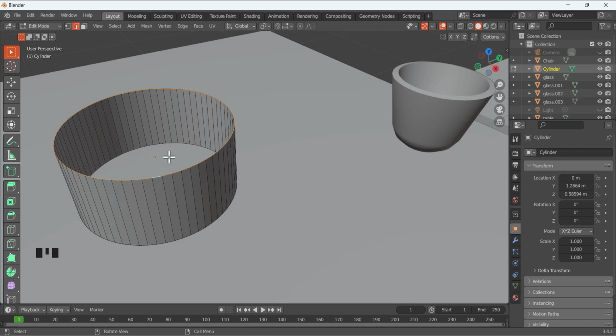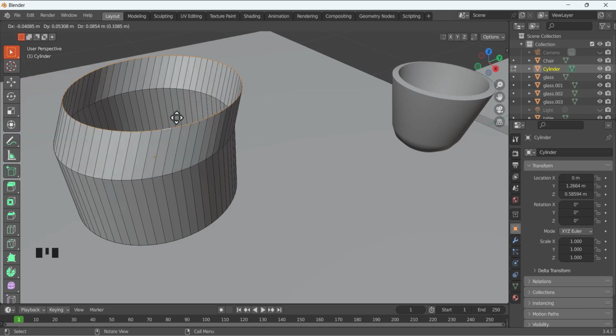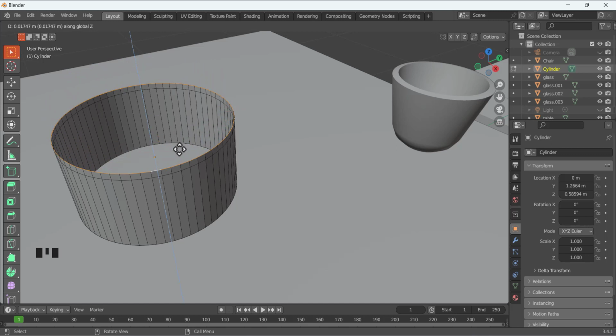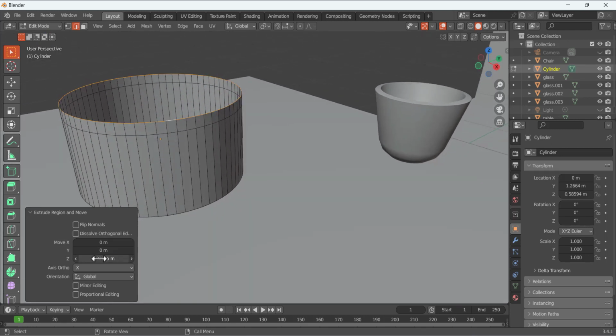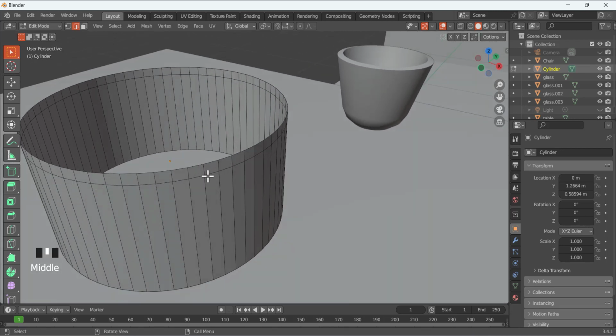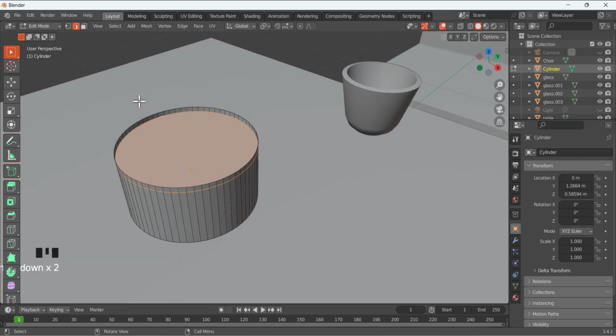in the Z direction. So we have extruded, but the Z is not selected. So select Z at this location. So we extruded it, and the distance of Z is here. So something like that. Okay, we just extruded this face here, and now I am going to select this bottom face by pressing Control and just press F to fill it. So we fill this face.